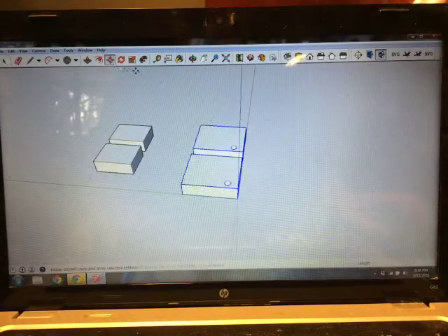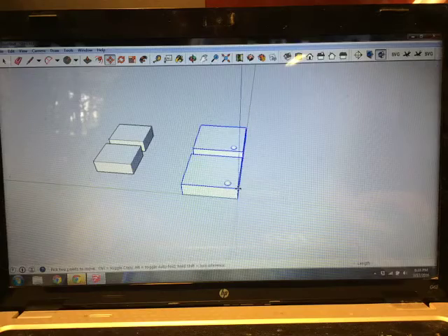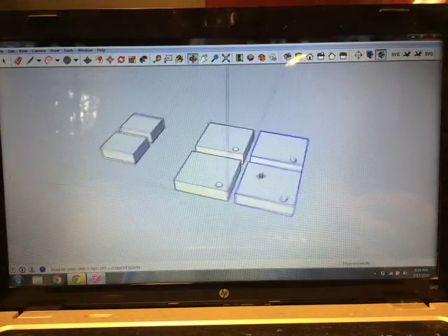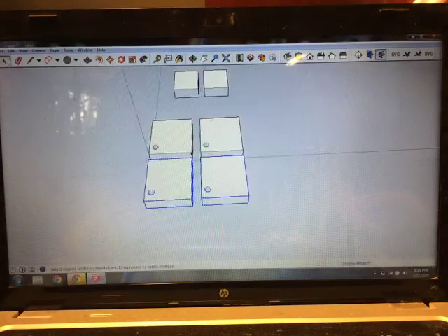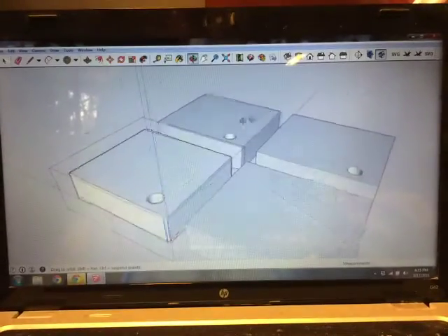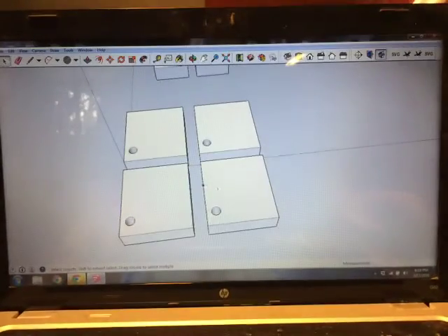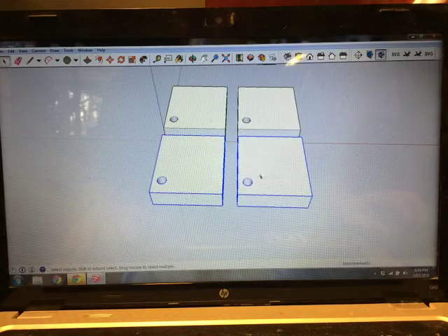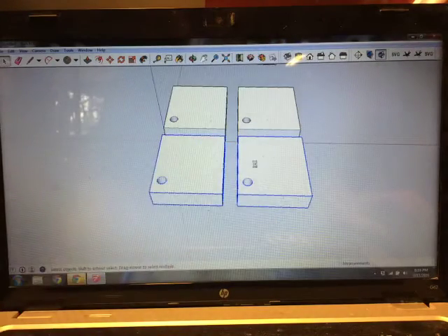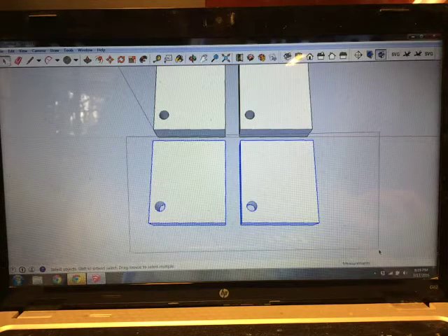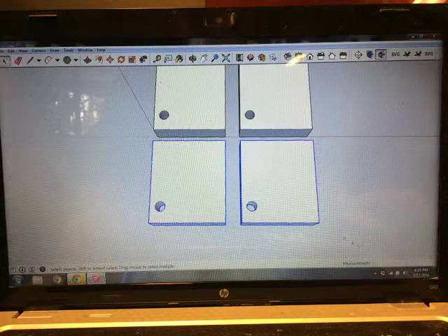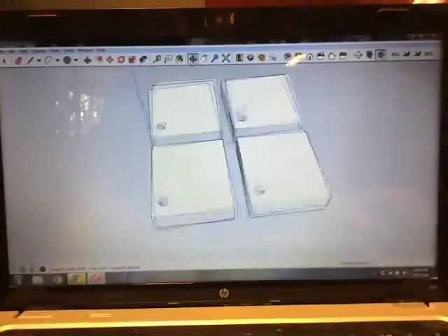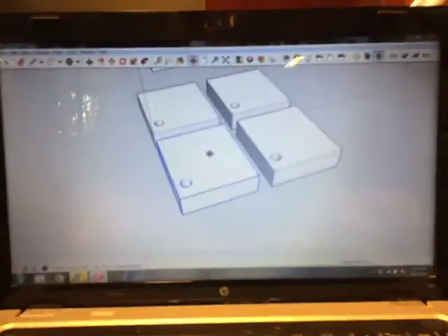Another thing you can do is copy multiple items. So if different stuff is selected, grab your move tool and control, then click it, grab it over, and set it wherever. If you alter one of these, they're all going to be part of the same component group. Let's say two of them you want a little bit different because you want a different hole somewhere else. Well, you can select those two. You can either try to only grab them, or if you grab everything from the bottom right, that's a super cool feature to know how to use quickly.